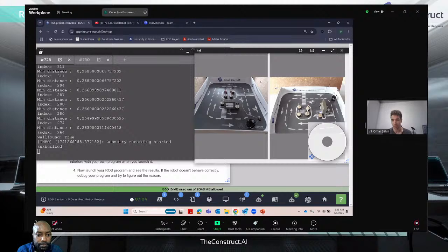When it's closer to 20 centimeters, it goes left, and if it's more than 30 centimeters, it goes right. So it's always close to the wall. And when it finds a wall in front of it, it turns 90 degrees. So that's how it keeps going around.